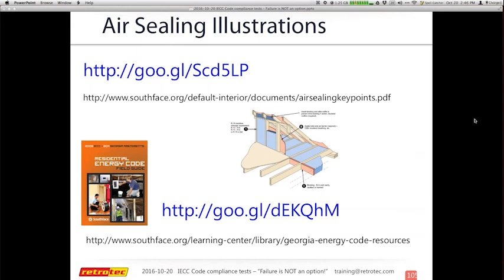Okay, so if we only lived in houses that had no windows or doors, I guess it'd be hard to get in or get out, but they would be pretty airtight. So you can see my thermal boundary in pink. I have an air barrier in blue. And then we start cutting things apart, making holes, making all kinds of issues around here. So I now have connections from my crawl space or outside to the attic.